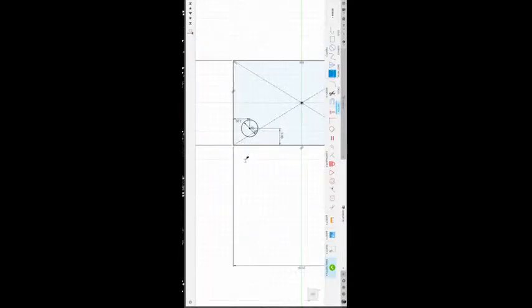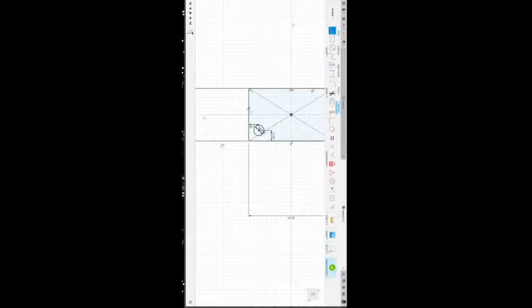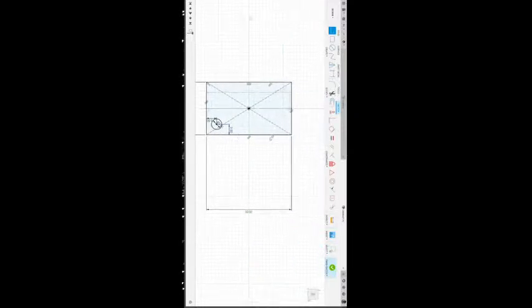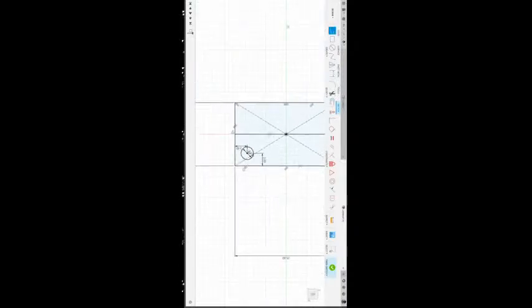So what are we going to do? We are going to recreate the other 3 holes from scratch. Here is a tip from my experience: you can just put a line in the middle and use the mirror command.